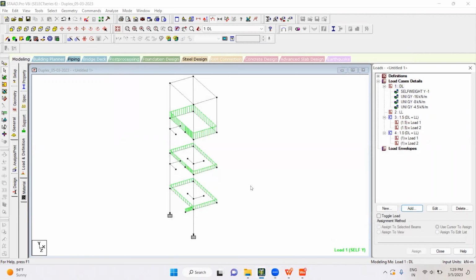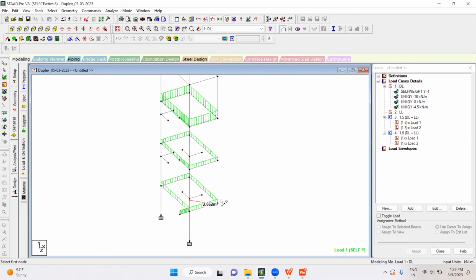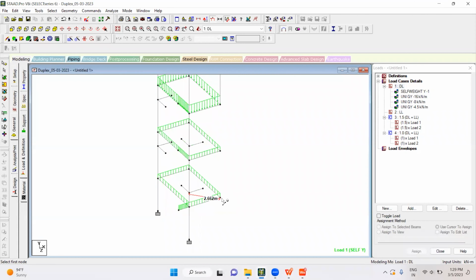Right now, I'll show you the same thing here. So I'll go to this. You can see the same dimension here. I'll select like this. And let me say up to this approximately 2.6. Now I'm taking like 6 meters, 3 meters approximately. 3 into 6, 18. 18 by 2, 9. Again, from here to here is 4.5 meters. I'll take like 5 meters only. 5 into 6, 30. 30 by 2, 15. So I'll add 9 and then 15.